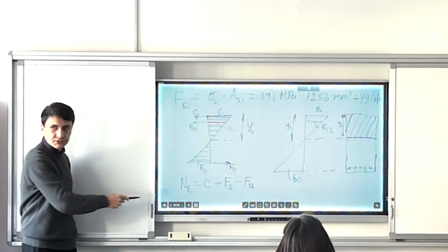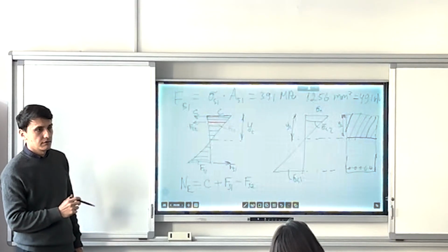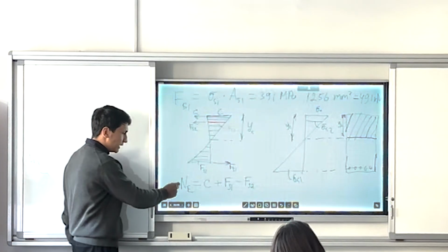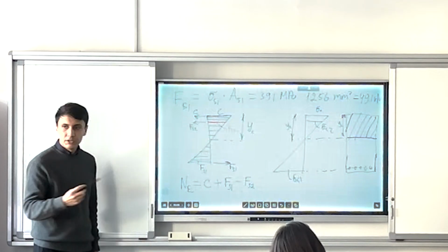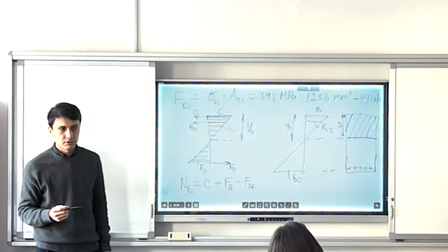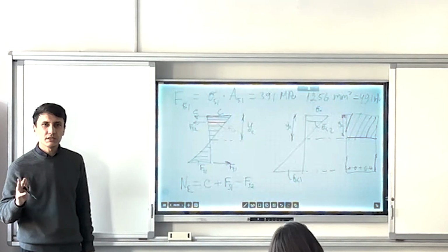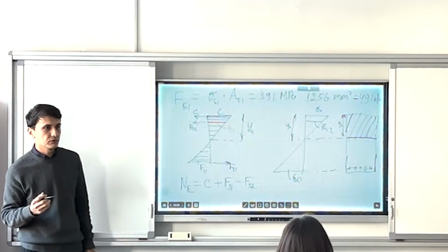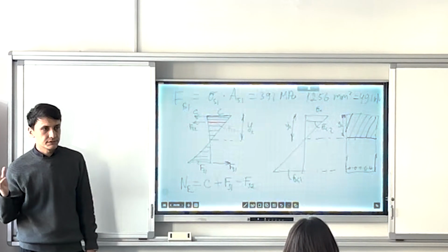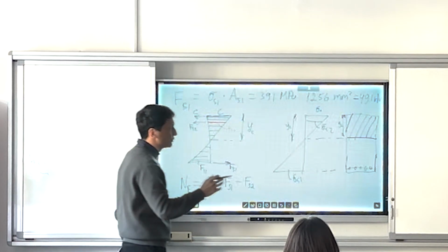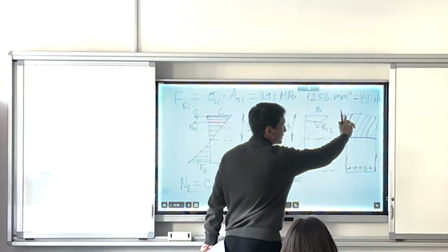Our axial force, which is the external axial force given at the beginning in the description of the exercise, was equal to 200 kilonewtons, right? So the axial force should be equal to the sum of internal forces. We have three materials contributing to the resistance of the section: top rebar, bottom rebar, and the concrete itself. But the concrete contributes only in the compressed part. The tensed part will not. So the compressed part is equal to YC.